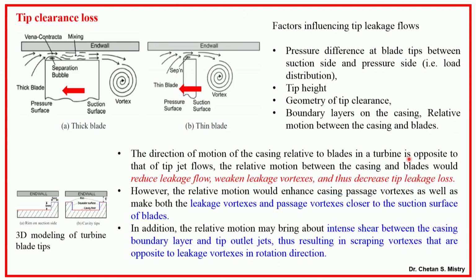We will see what exactly and how exactly we need to understand. Suppose if I am talking in terms of, say, tip clearance, here similar is the scenario. What it says is, the smaller your tip clearance, the more the loss will be reduced. But if you look carefully at what is happening, my rotation is from the suction surface towards the pressure surface. That's my blade rotation.